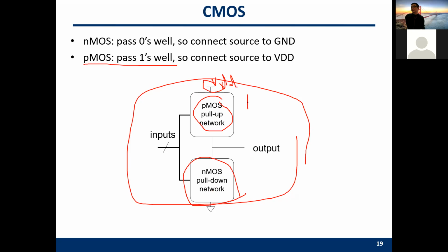Better 1 means it has less noise. For example, it can pass a very strong 1. Of course, the NMOS can also pass 1, but the 1 passed by NMOS may look like this, so the signal quality may degrade.